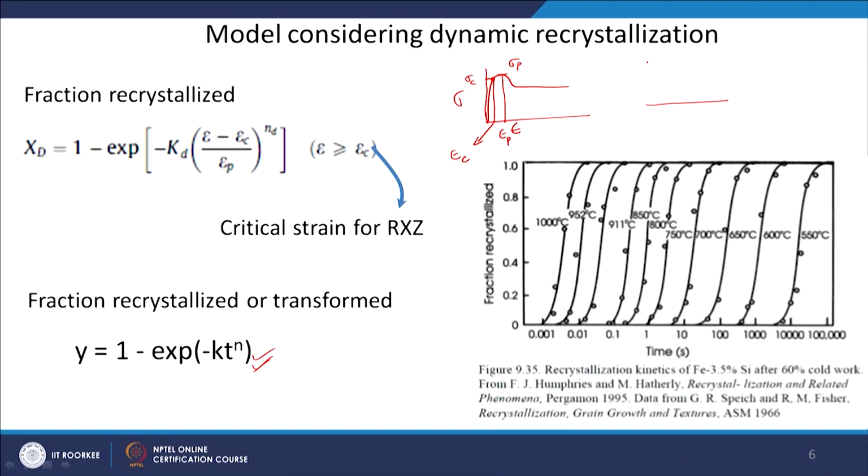Then there is a sudden increase in the nucleation as well as growth, so the fraction transformed increases, and then as the volume of the parent phase becomes smaller and smaller, the kinetics decrease again. So, it has a very typical S shaped curve, initially increasing exponentially and then decreasing.